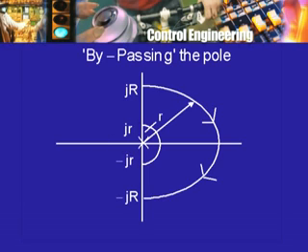So, the contour now consists not just of the straight line part of the j omega axis and the semicircle, but it consists of 3 parts, or if you wish 4 parts. There is this small semicircle which is like a bypass or a detour into the complex plane, the right half plane. Then there is the big semicircle which we had as before, and then there are these 2 parts of the j omega axis which are symmetrically situated.